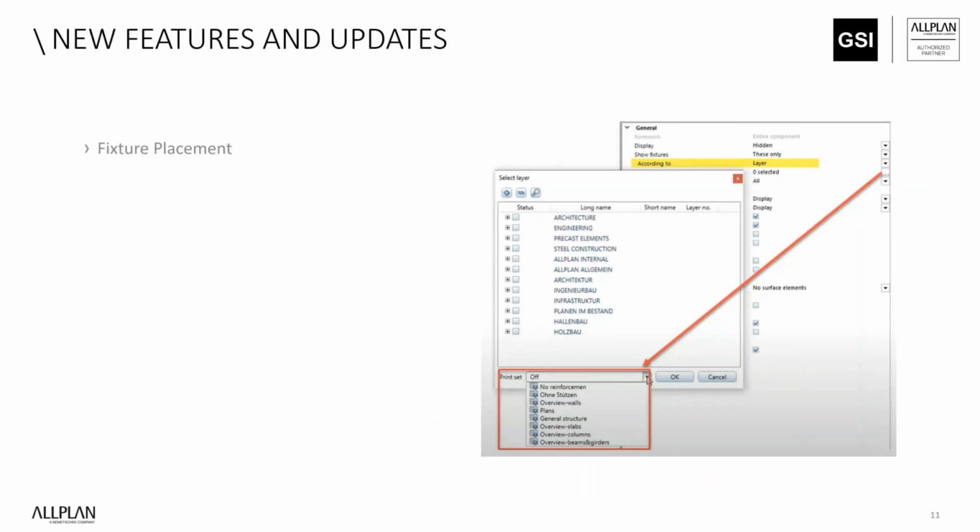So for the option in the element plan settings, previously in the views options, on the show fixtures, you can only see the defined fixtures, or just one option that you need to select what fixture you want to show. But now they already added this layer wherein you can choose this layer to be shown on that view, or I mean a view, right? So this feature will help you to organize clearly or show clearly on the shop drawing or the element plan what fixtures you actually want to show, right?